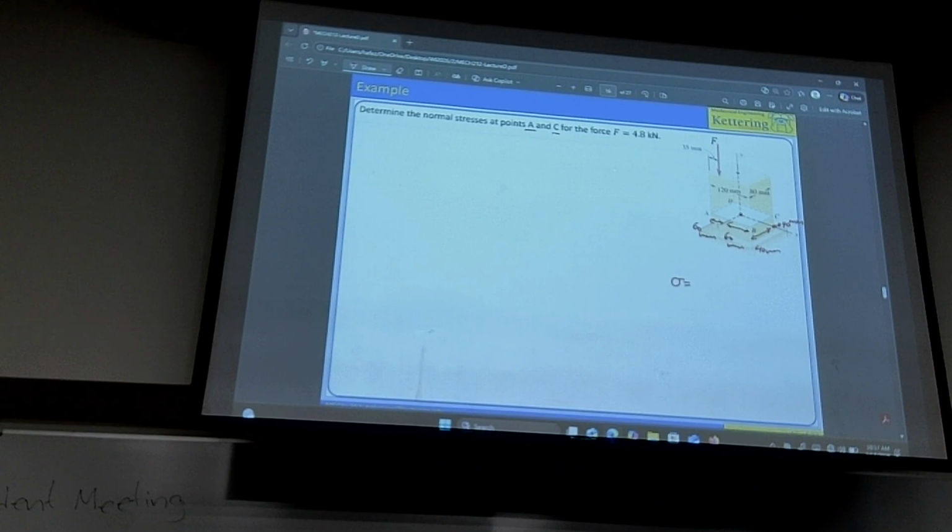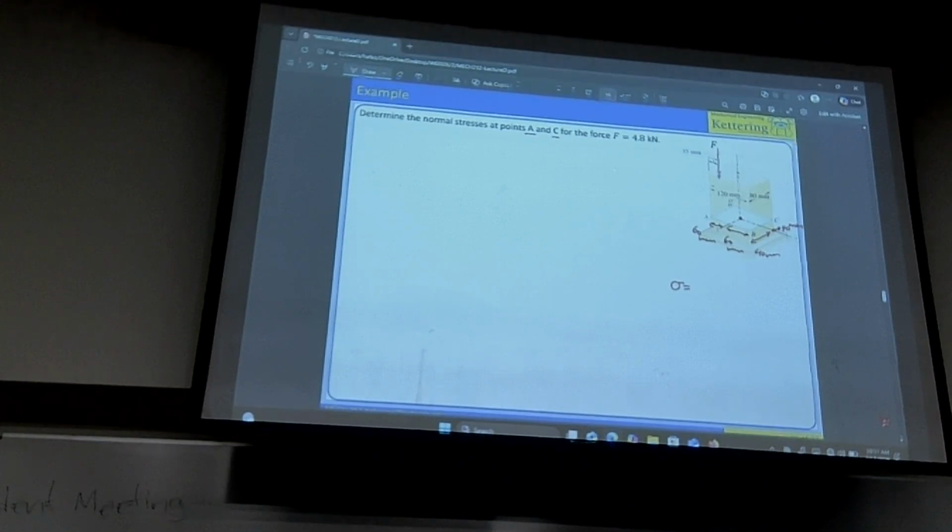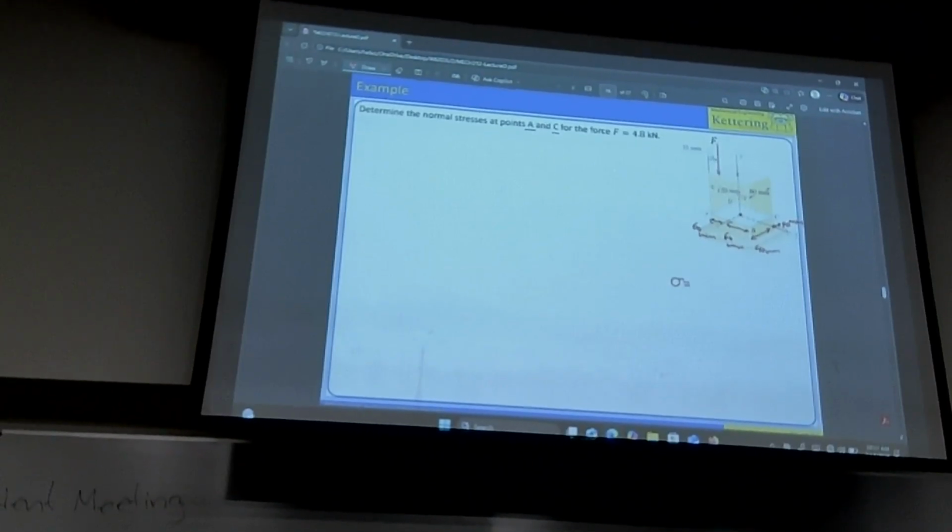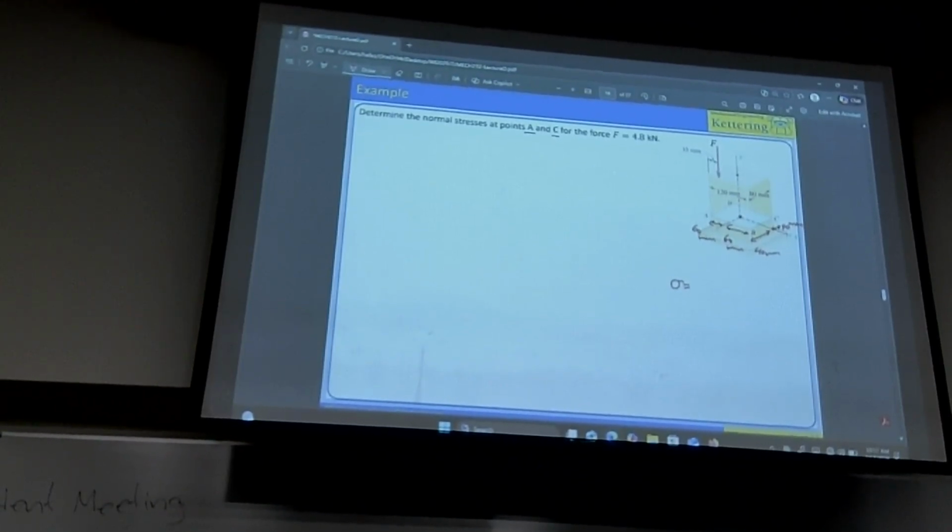Okay. All right. So we said enumerate the load effects in terms of axial and bending. So axial. Whenever you see a load like this, pushing or pulling, yes, there is F over A. You're pushing, it is negative. So negative F over area is there. Negative because you're pushing again. All right. Now, let's talk about bending.